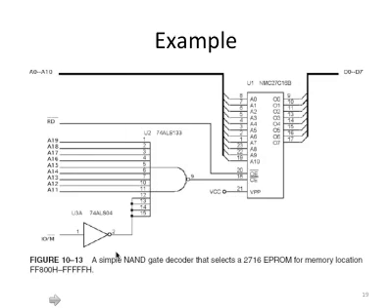On the left side here, these are the signals coming from the microcontroller or microprocessor. The microprocessor, in our example, has 20 address lines, so you can see from A0 through A10 and then from A11 to A19. Also, it has control signals coming from the microprocessor.